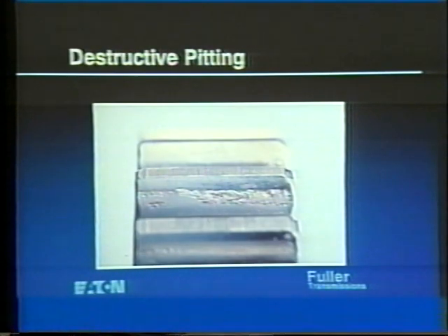The pitting on this gear is well advanced into a destructive stage. The pit craters are larger and deeper. The gears and mating gears should be replaced.